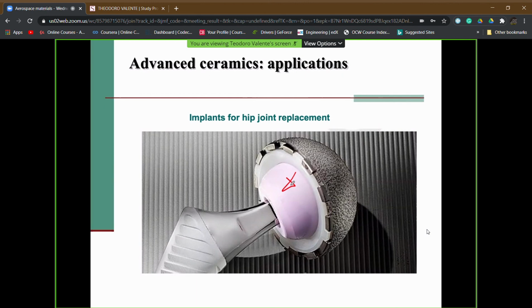In other cases, it is made using zirconia toughened alumina, aluminum oxide, in which we can disperse, using the same concept as before, a tetragonal metastable zirconia phase, which can be activated in terms of transformation to monoclinic by stress again, thus increasing the fracture resistance of the head of the ceramic implant, that is, increasing the K1C of the material itself.